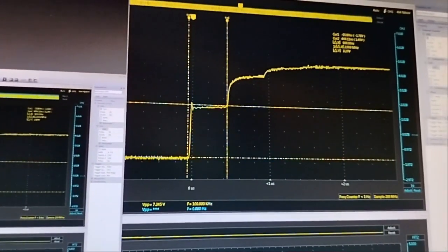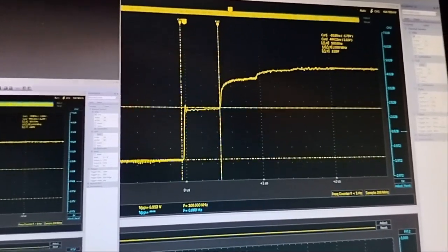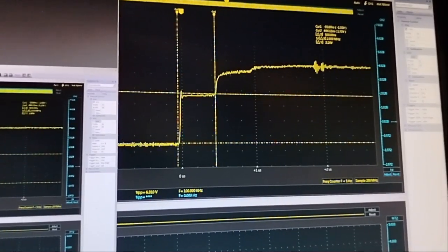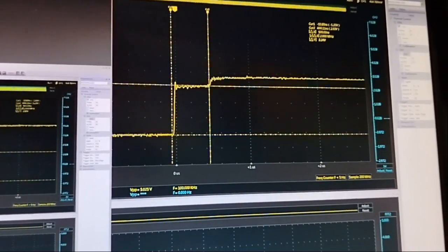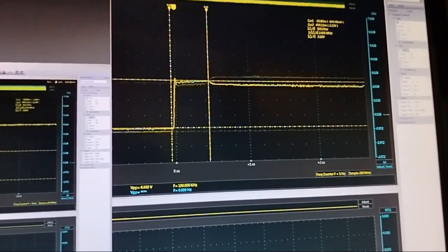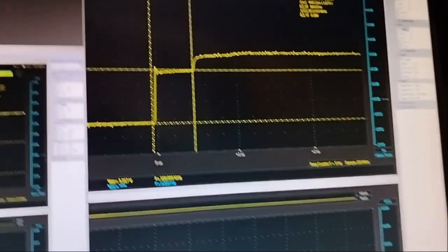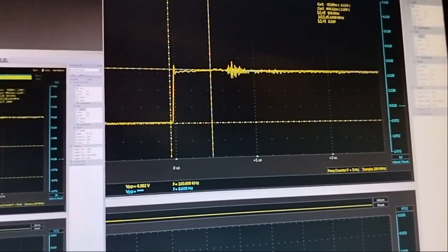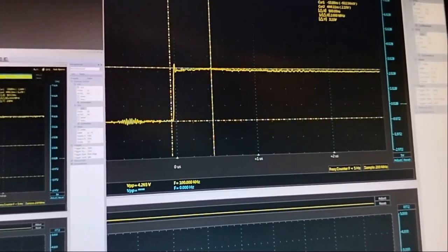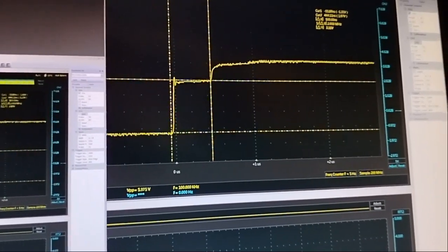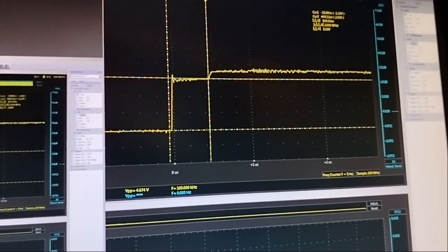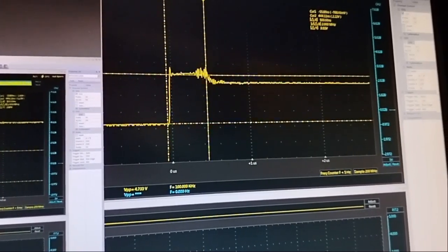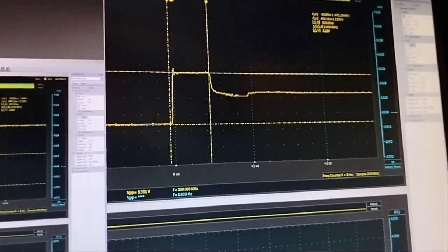So I'm moving it, decreasing the value of the potentiometer, less and less, up. Oh, you see how it works. So at this moment I'm reaching the impedance of the cable, and we have no wave reflected from the end of the cable. And if we continue to move downwards, decreasing the value, we have the reflection again, but with the opposite sign.